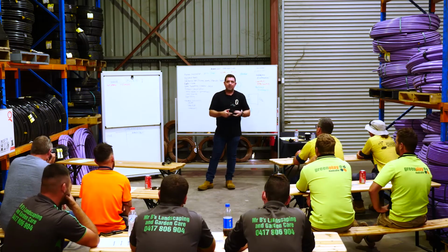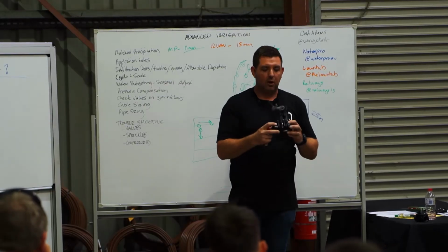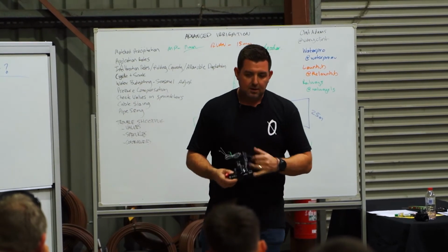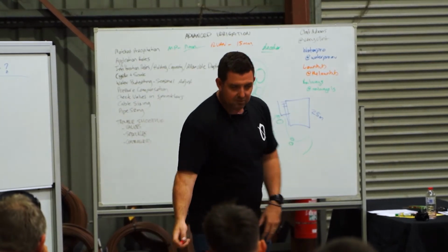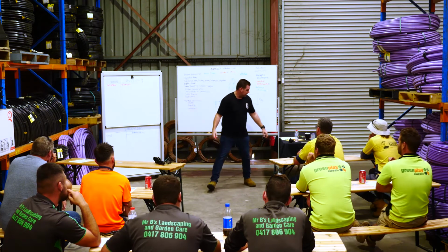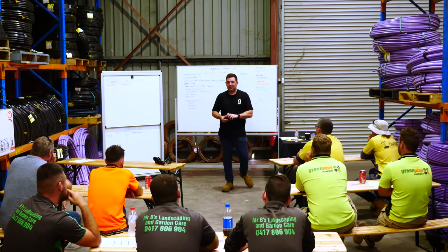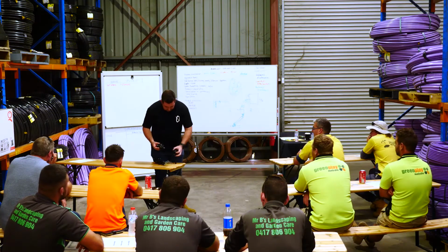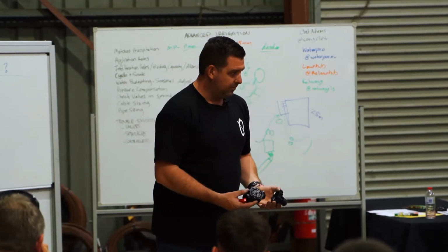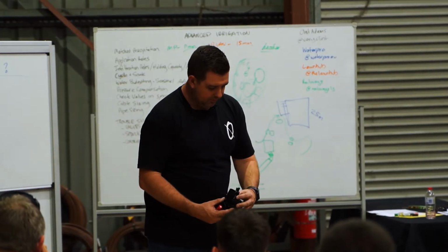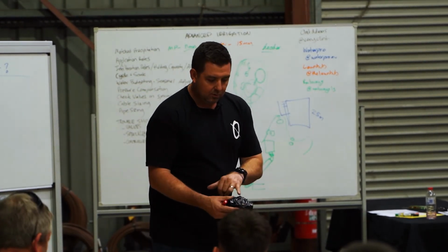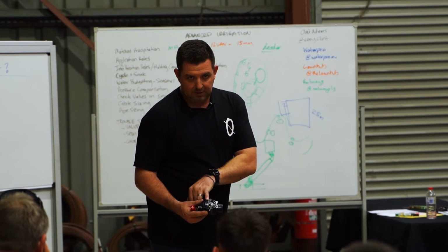Most commonly, if there's a flow issue, it's because there's something inside the valve. So there'll be a rock or something inside there. If you've installed the system yourself, obviously it wouldn't be a rock, because you guys are all so good at what you do. But if you're going out and troubleshooting another person's work, all of these valves come apart the same way. You undo the screws on the top, you take the bonnet off, you're left with a diaphragm. Not all springs are captive like that, so be careful.